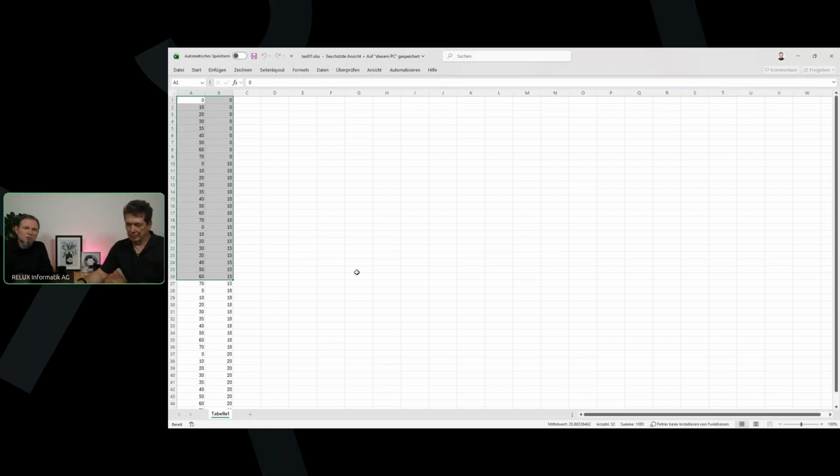So we can say, I have this amount of grid points, these grid points have an average value, and this average value is representative for the area. So we can say this area has a maintained average illuminance of whatever, or uniformity of. This is possible because each grid point represents the same area.